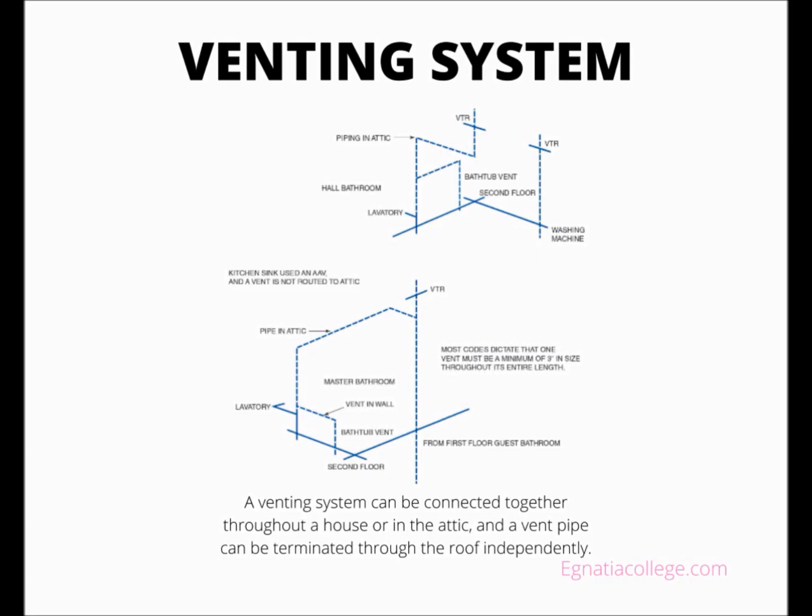Vent fittings are responsible for circulating air and draining moisture, as opposed to discharging wastewater. Most codes dictate that all fittings used in a vent system must adhere to drainage regulations. However, many codes allow variances in the fitting selection between these two systems. They allow standard radius fitting in a vent system where long radius fitting would normally be dictated if the piping were a drain. Terminating the vent pipe through the roof requires an oblong hole to be cut with a reciprocating saw from inside the attic.